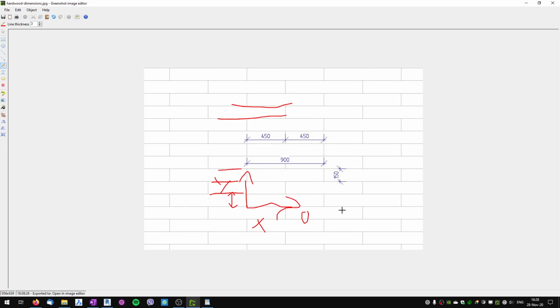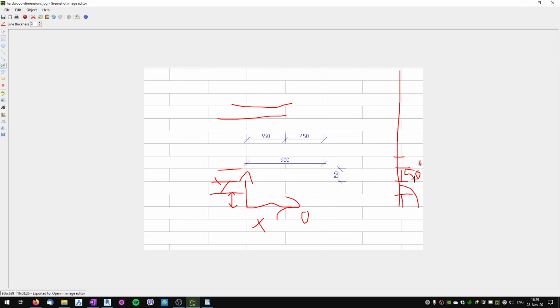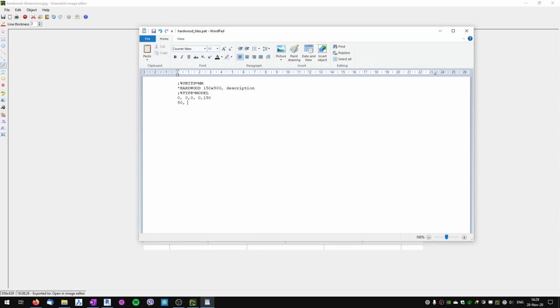Now we will start to create these lines, and this is actually one line, but it's dashed. It's 150, and then there's a space 150, and then there's 150, so it's just one line and it's dashed. The angle of the line is this one, so it's 90 degrees. And this is all we need to create this line. So let's start. We started already a new line. The angle will be 90 degrees, comma.